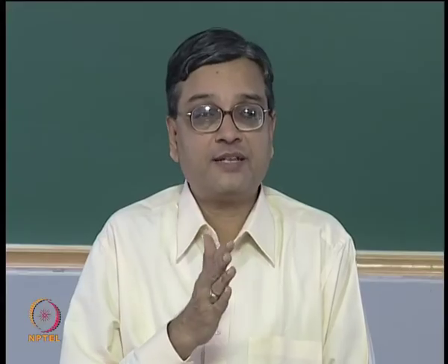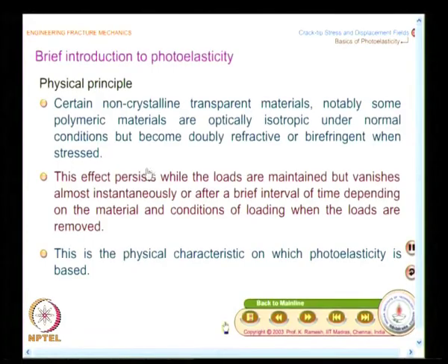So, this is the basic physical principle. A crystal by nature is a birefringent material, whereas here the birefringence effect is temporary. As long as the loads are maintained, it will behave as doubly refractive. When the loads are removed, it will behave as optically isotropic. Whatever loads are introduced really cause this to behave in a birefringent manner. So, by looking at the birefringence effect, we can calculate the stresses. That is the basis of what photoelasticity is.